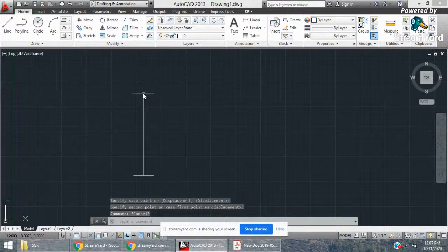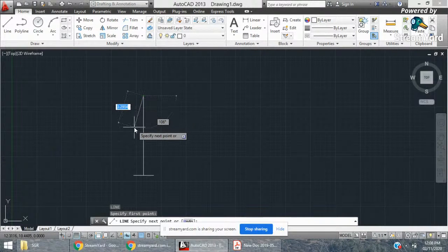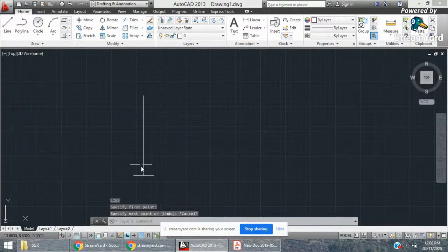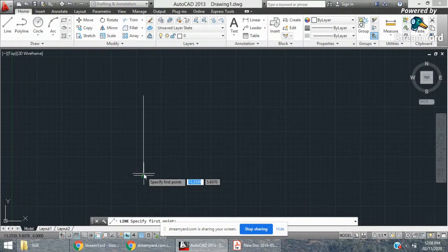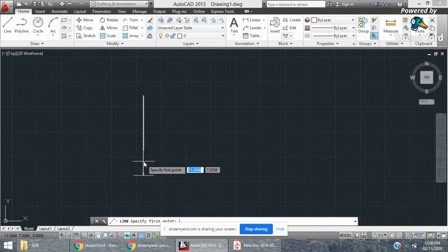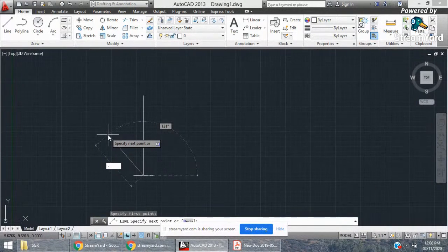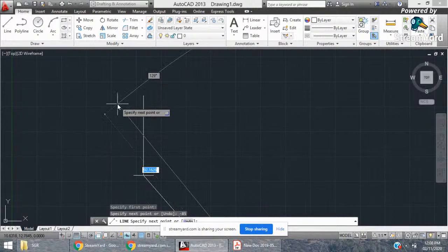From here you have to take phi equals to 5 degree angle. So from here we will draw alpha angle from here. So 90 minus 5 equals to 85 degree. So I will take 85 degree here. Okay, and it is going on opposite side, so it will be minus 85 degree. Remember, batter angle is given to you as 5 degree. So I am taking from this.